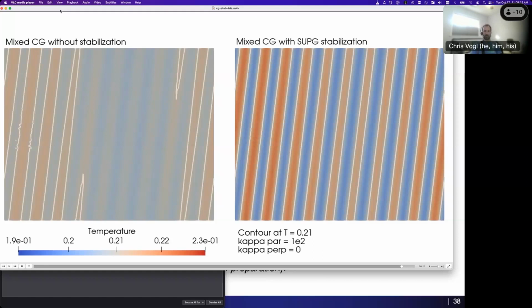So the plots with the iteration counts were for the problem that we used for the DG test case, which was 3D and periodic in Z, and it had a prescribed initial temperature field that we then used as a steady state, or we formulated the problem in a manufactured way so it should be steady in time. We didn't integrate for a long time, so we're not accumulating time error, and we use relatively small time steps, and then we use that to measure the spatial discretization from the prescribed initial condition that's more or less exact within the finite element space.